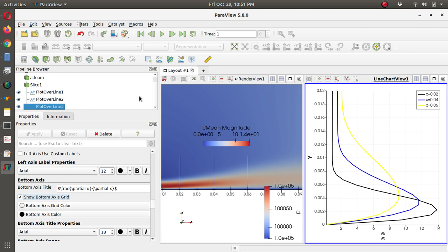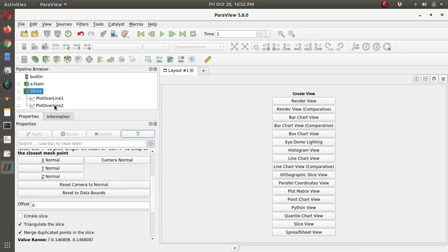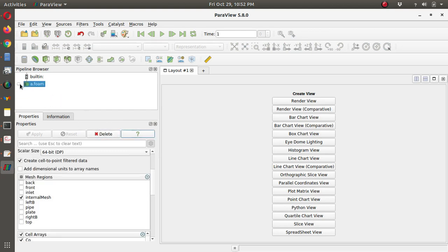Now we will come to the three-dimensional plot, as we have the values of the Q function. It is able to present the vortex structure involved in the flow field, and it is used to present the vortex structure for instantaneous flow. Okay, not in the mean data, not in the average data, but in the instantaneous data. So we already have the instantaneous data, and we are now planning to present plots of the Q function. So I am deleting all the plots and coming back to the main data.